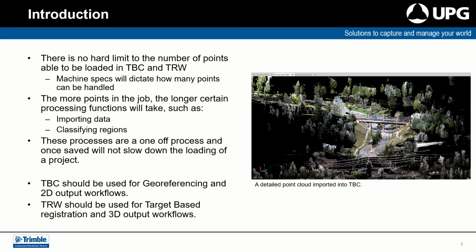When looking at Trimble Business Center and RealWorks, as mentioned before, there's no hard limit to the number of points, and the machine spec that you are using will dictate how many points you can handle. The more points in a job, though, the longer certain processing functions will take, such as importing the data and classifying regions. In this case, these processes are a one-off step and will only be needed at that initial stage, and once saved, they will not need to be run again, as that process will be saved as part of the format. It's worth noting, though, for particularly large projects, it might be worth splitting up into smaller projects and working on smaller projects to help with speed and efficiency of data capture.